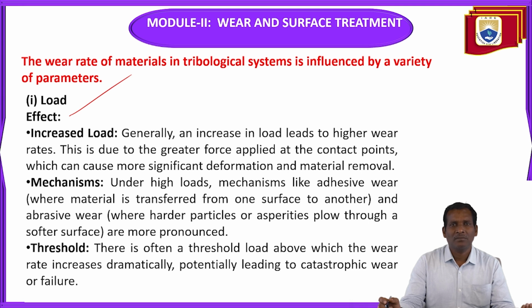Under high loads, mechanisms like adhesive wear, where the wear material is transferred from one surface to another surface, and abrasive wear, where harder particles or asperities plow through a softer surface, are more pronounced.